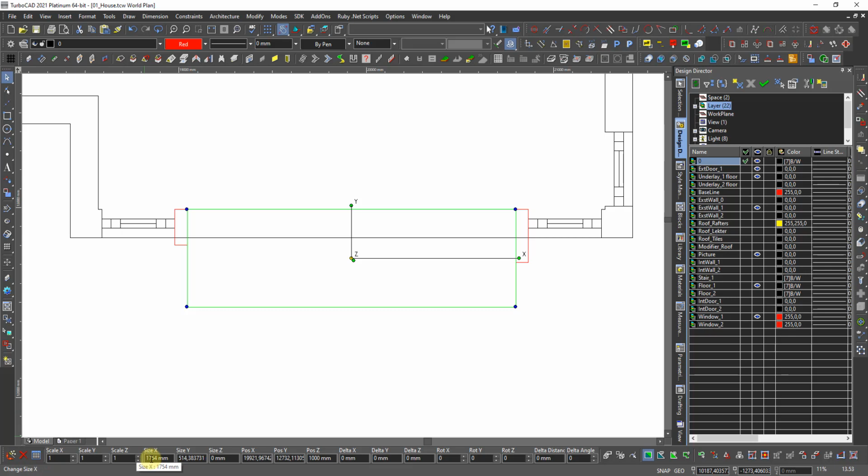And 54. Meaning on this, then there should be 90, so I'm missing 36 millimeter. That's not possible. 36 divided by 2 is 18, and I cannot move this 18 millimeter more back. But the plate coming on this wall will then be coming into the window. I don't believe in that.